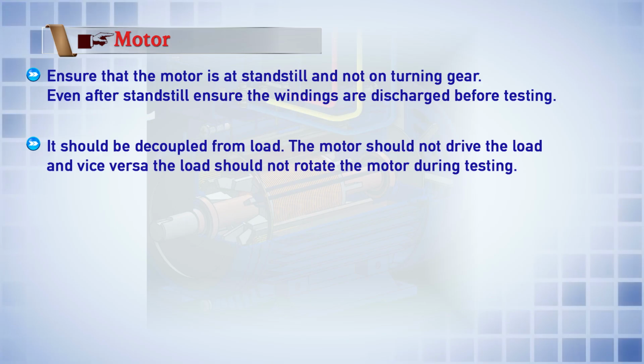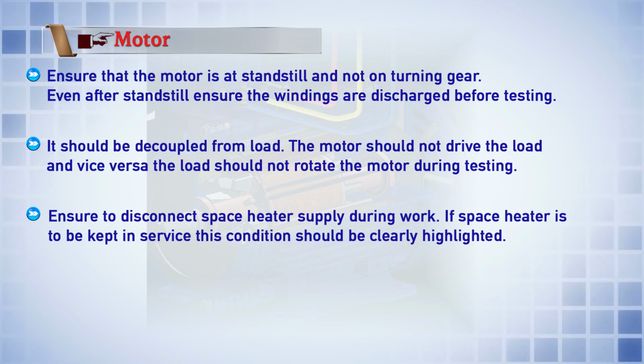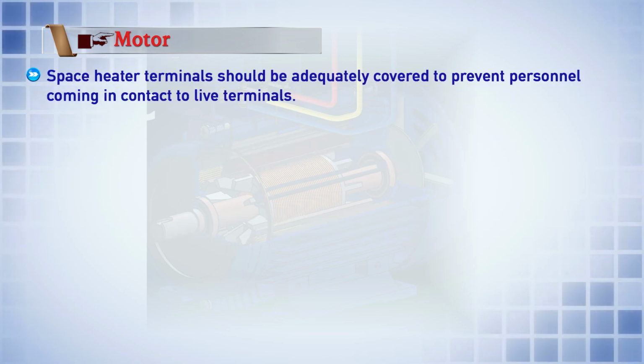Second point, you have to ensure that it is decoupled from the load. The motor should not drive the load and vice versa. The load should not rotate the motor during testing. Ensure to disconnect the space heater supply during work. If a space heater is to be kept in service, the conditions should be clearly highlighted. Space heater terminals should be adequately covered to prevent personnel coming into contact with the live terminals.